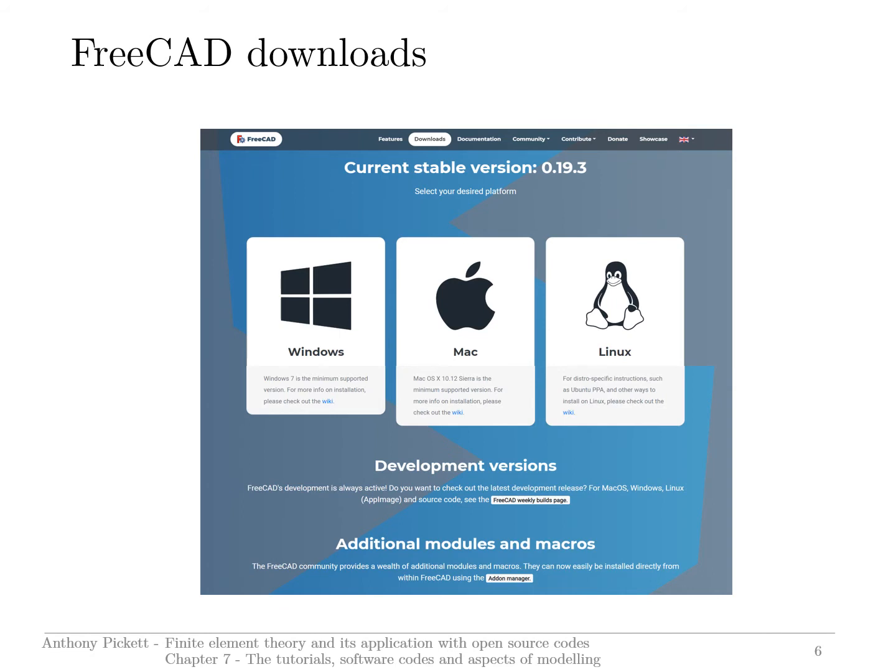This is the main download page for FreeCAD and Calculix. If you do install FreeCAD, it is best, as always, to take the latest versions. It's available on Windows, Mac or Linux. I've always used the Windows version, and it's a very straightforward installation process, very standard. And just to be aware, if you do install FreeCAD, it does come with Calculix already integrated, so there's no extra software to install there.